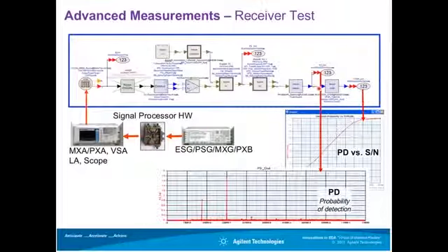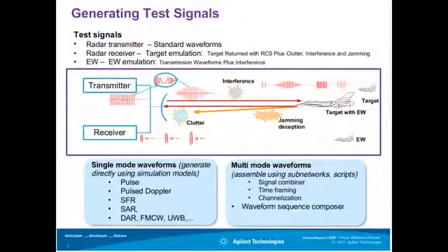For example, this is a pulse Doppler system. In the time domain, as we already showed, you have no way to detect the return target. However, going through this type of signal processing, you will extract the pulse, and you can do the detection probability. So in this way, the system view platform extends the measurement capability for you.